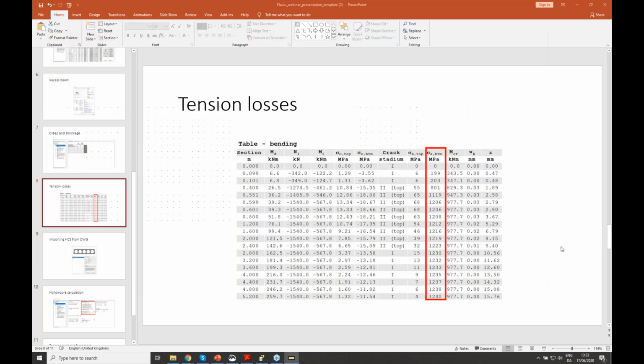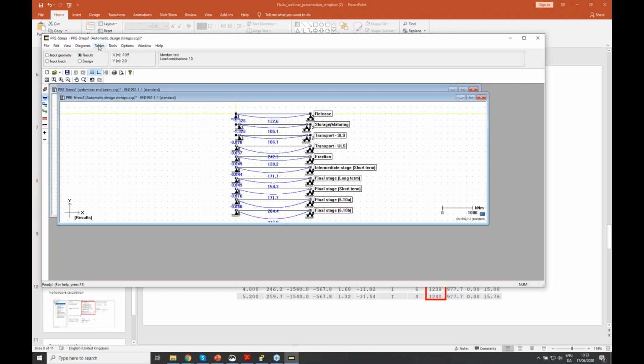Basically, what you see is the stress after the losses that pre-stress takes into account according to that formula. So if I had 1300, which I think I had in this example, I see that it's a linear increase from the end of the beam towards the interior, and it rests around 1240 for my final. So basically, in this case, my loss would have been 60 megapascal. Let's perform this calculation here too.